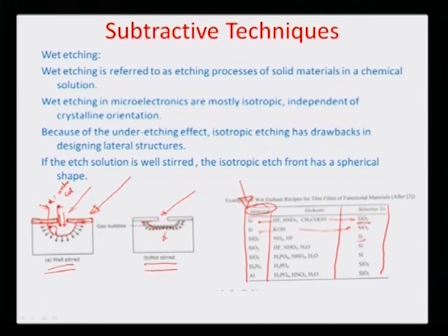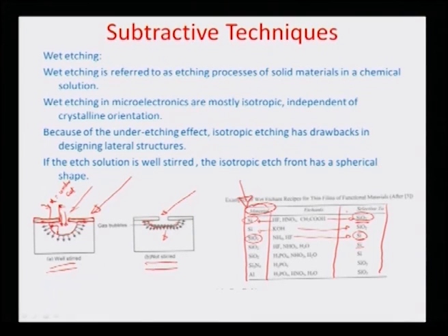Or it will not etch Si anymore in this particular illustration where NH4F and HF combinations are used. So, there are certain etchants which etch away one material and are selective to silicon, or they etch away the silicon and are selective to SiO2. The combination of these can be used for a variety of etching architectures that can be realized accordingly. Thank you.